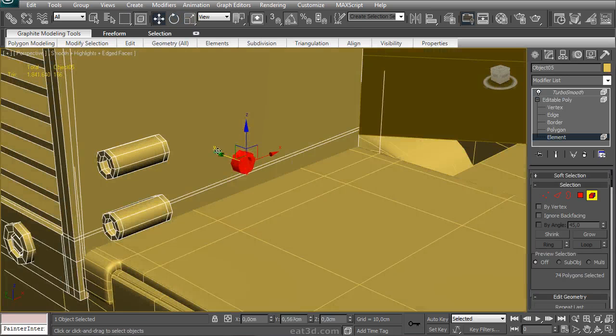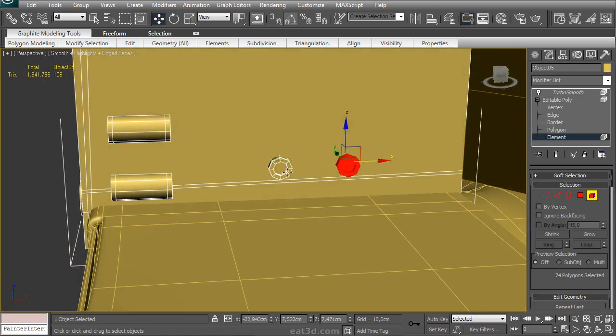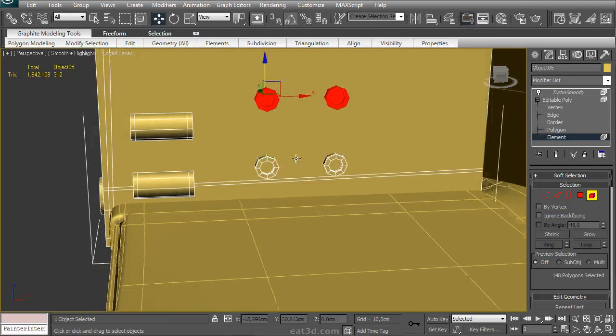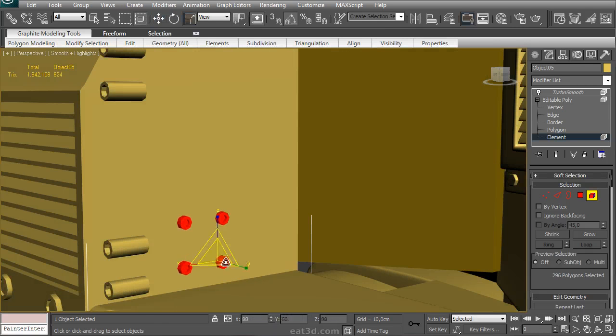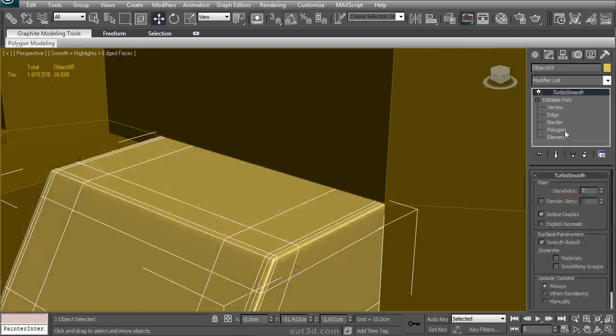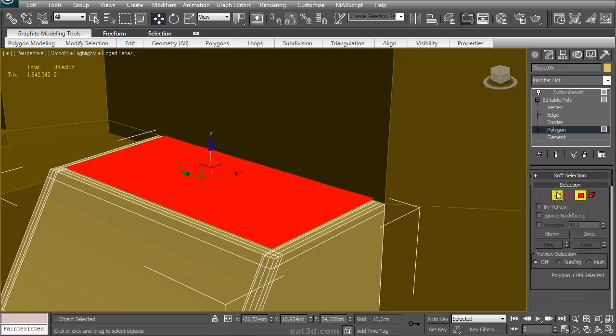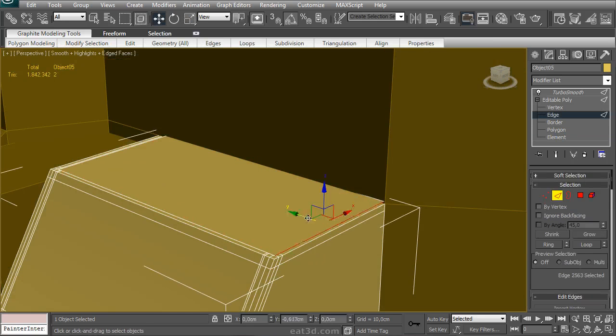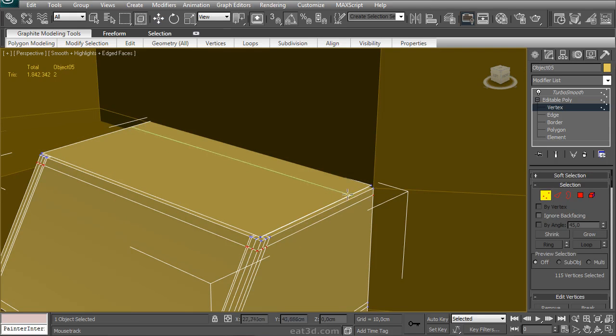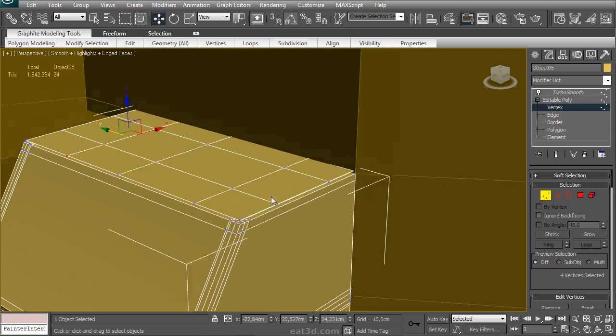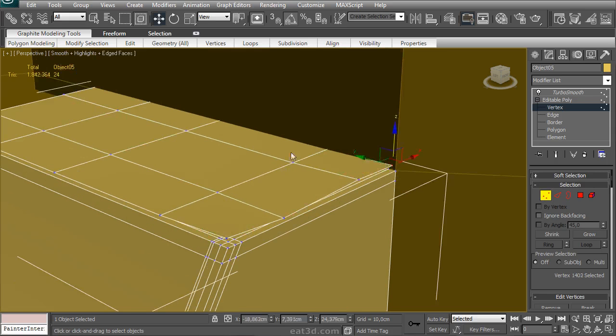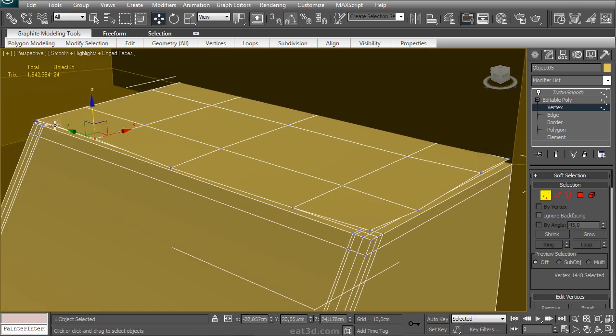Another advantage is I can use these shapes to create another detail, which is like this square with one of these cylinders on the corners. So I'm just moving that around. And then I'm adding a top part here. You see that I took a plane and then I duplicated that. And then I'm just adding a few segments to that. It's a quick way to add geometry. Just take a plane from an object you've got selected, shift move it, and you've got some new geometry. I added some segments to move these points around.